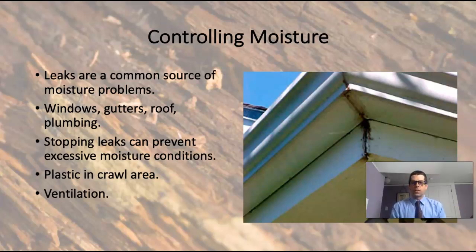Providing adequate ventilation is very, very key, okay? Assume that there's going to be moisture accumulating under the house, and then provide a way for air to move around under the house and push that moisture out.